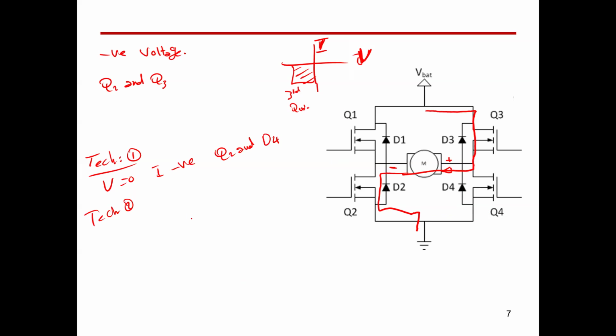If you use the other technique, technique number 2, with the pulses we have in the previous slide, you return back again to the other switches. So in this case, the volt will be returned to positive again, and the current is going to be negative. And positive volt and negative current means you are working in this fourth quadrant. So for that, guys, we call it 4-quadrant operation.